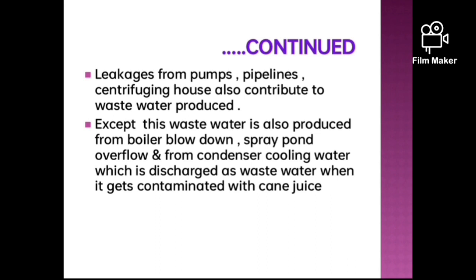Leakages from pumps, pipelines, centrifuging houses also contribute to wastewater produced. Except this, wastewater is also produced from boiler blowdown, spray pond overflow, and from condenser cooling water, which is discharged as wastewater when it gets contaminated with cane juice.